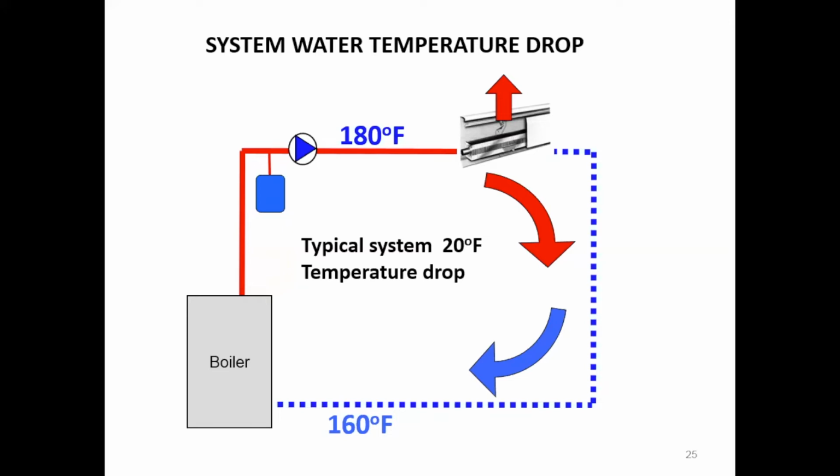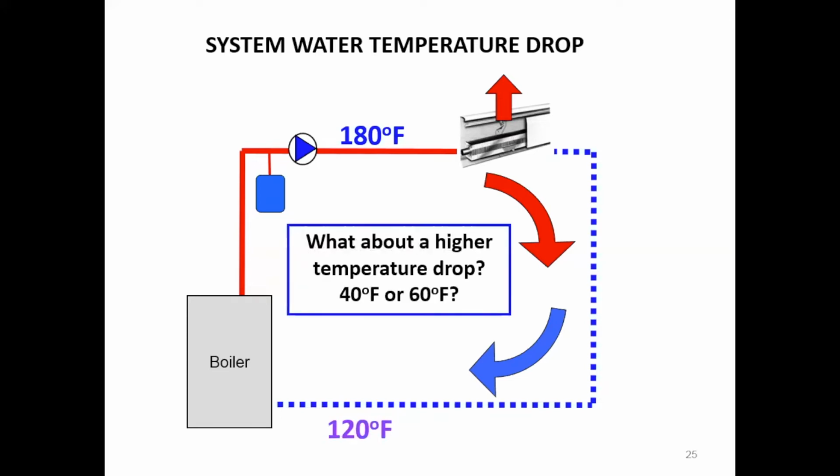But from an aspect of performance, the question then becomes, can I get to a larger differential temperature or delta T or drop in the system? Let's not do 20, let's do 30 or 35 or 40 or a higher number. By opening those up, I may have to still, for the application, come out at a high temperature, but if I can open up the delta T, I'm bringing down my return water temperature, and the return water temperature is really what matters, okay? In a lot of situations, it may be a little bit of oversizing, or it just may be how I apply.